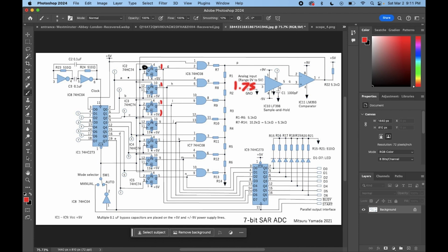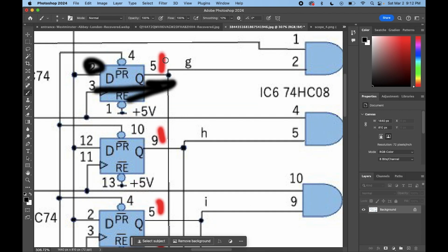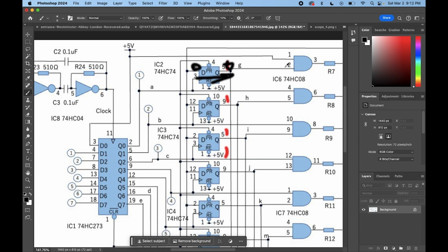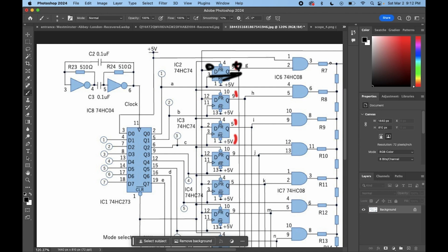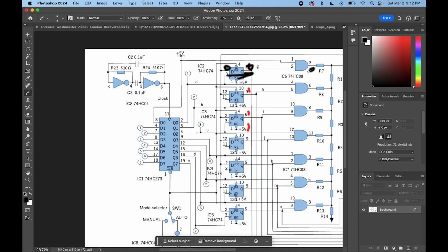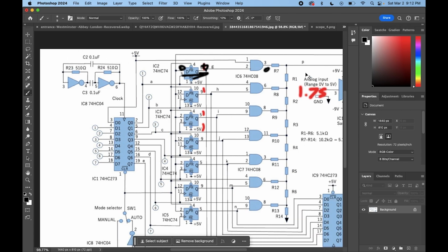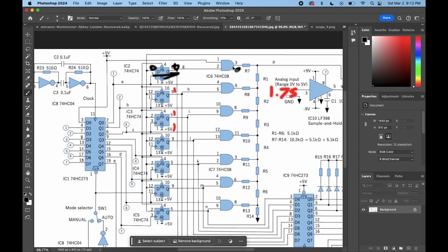So we now have a high on this, which is the clock pin of this first flip-flop. So this updates the first flip-flop, and since there's a 0 here, this 0 is shot out and it gets to the other side of the flip-flop. So on the other side of the flip-flop, this one now becomes a 0. So then we have a 0 on this AND gate with a 1 up there. So then it updates and there's a 0 on this resistor here, which means that there's no longer 2.5 volts being generated by it, which is half of the supply.